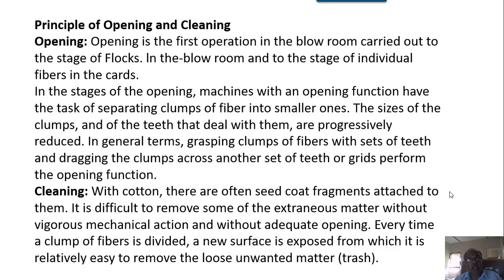There also, advantage is taken of aerodynamics: trash being heavier compared to the opened cotton, in that trajectory of transportation the trash is likely to be ejected out. So these kinds of principles are used, plus gripping, tearing, ejecting, etc. These are the methods through which the cotton is made to open.